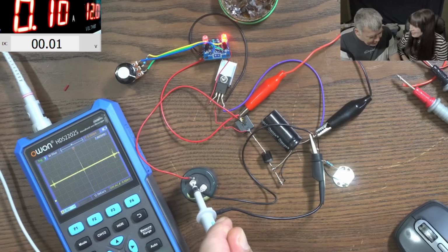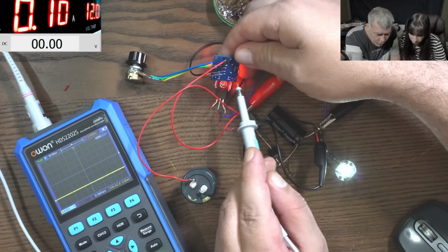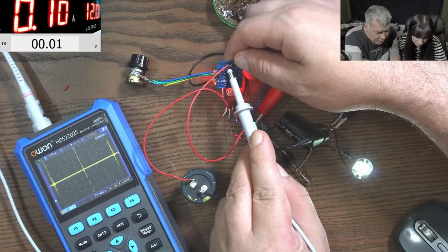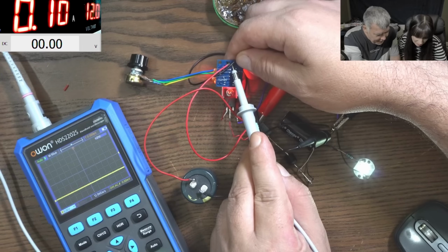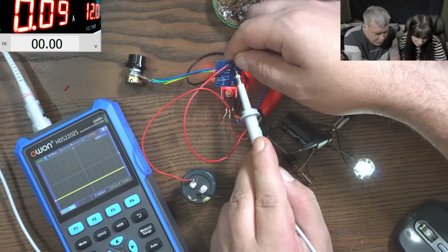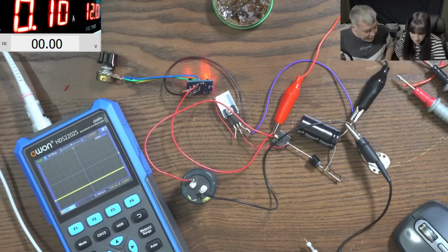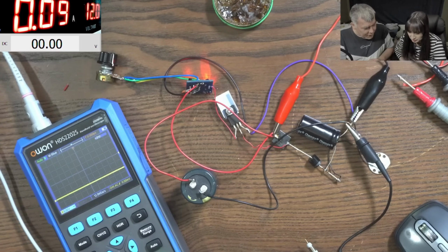So wires are not good, especially when I put a big one. You get your power modulated. If I check the power here, this is plus, this is minus. You modulate the power going to your MOSFET driver, and it will affect the functionality of that one. So what conclusion can we take from this? Never use wires. Remove the wires.